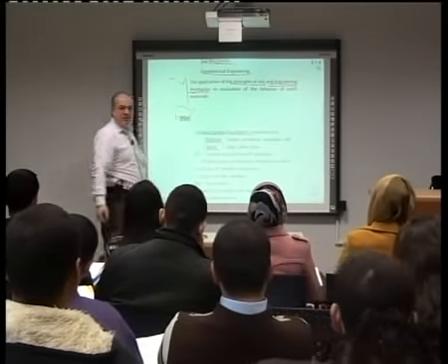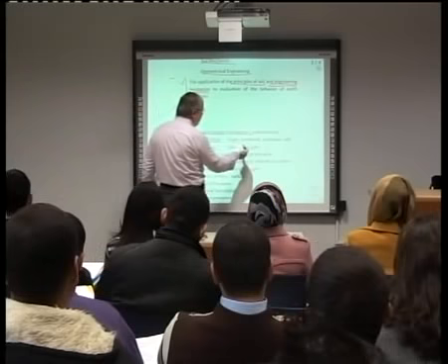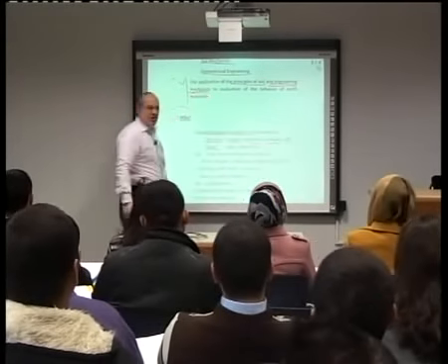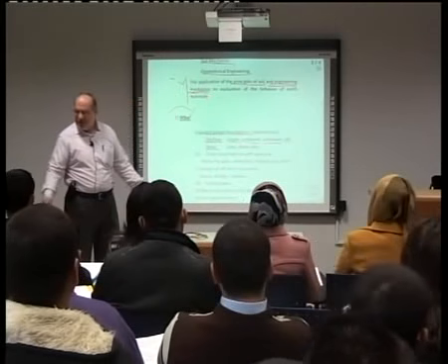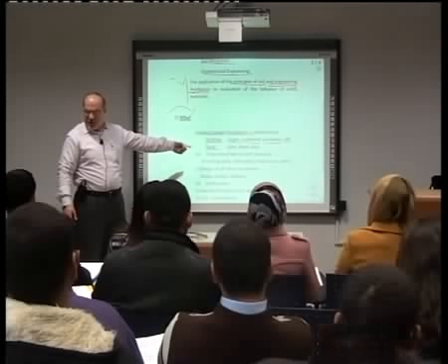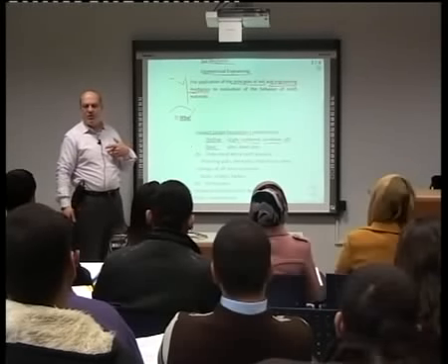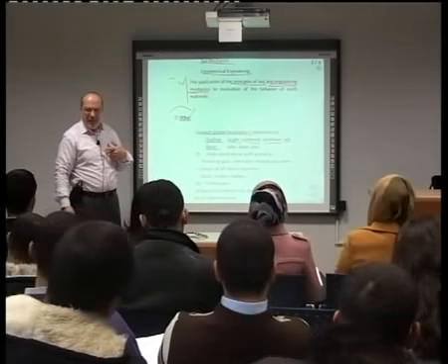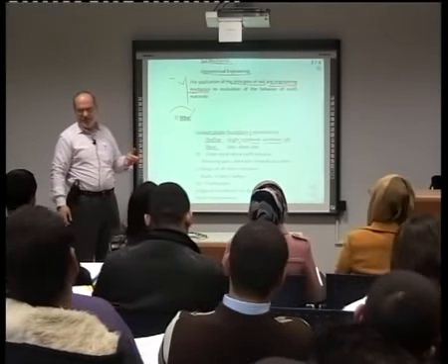And I have to choose which one is suitable for this building. Whether it is single, combined, cantilever, raft, strip, strap, whatever. These are all types of shallow foundations. I have to choose which one is suitable. I cannot choose that without being good in soil mechanics.